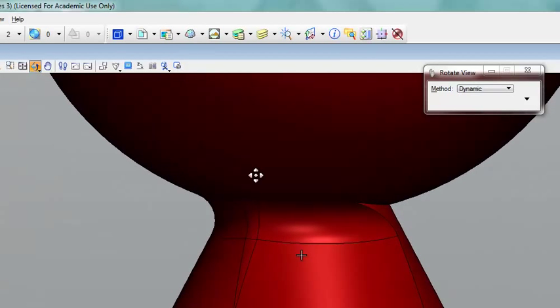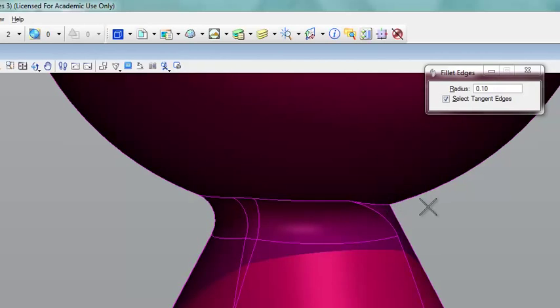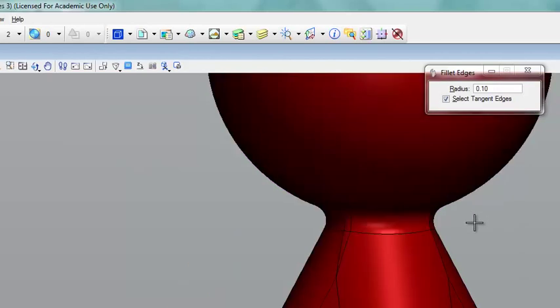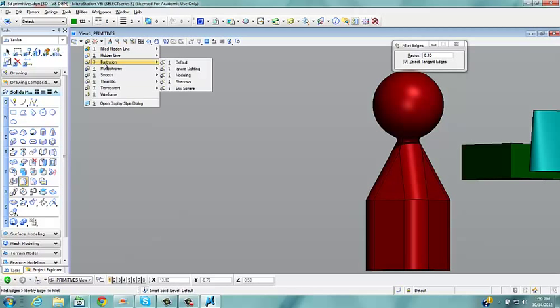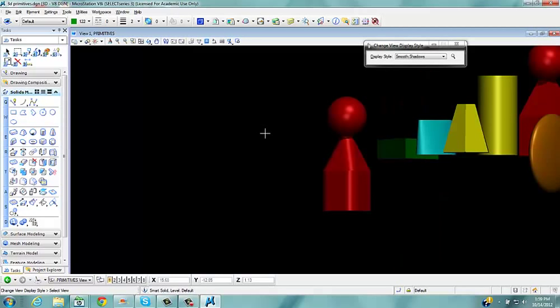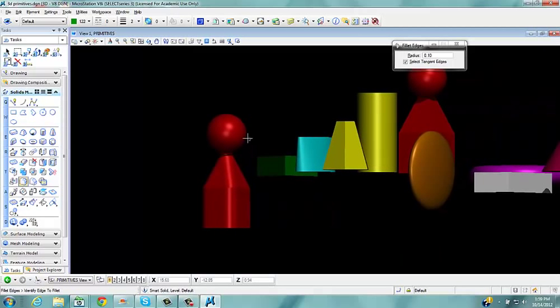Very nice. Sometimes the view that you're looking at just doesn't look like it. So you can see one more edge here, I think. This one. So see how that smooths that out? If we actually look at this, we're looking at right now as an illustration. If we look at it as smooth with shadows, we see that we get a much more smooth looking operation. And we can even do more with the edges. Let's put a 1 inch radius.